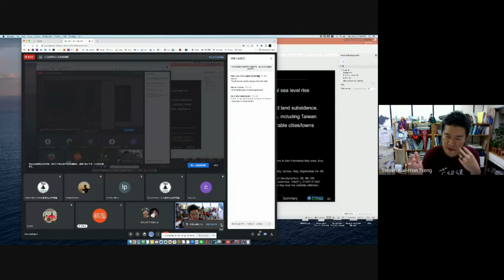So the error budget is very low, some millimeters remain. To combine all this error budget together, the accuracy of a single pass or a single sector of altimeter measurement is 5 to 10 centimeters. So we need a very long time series to fit the line and to get the rate.